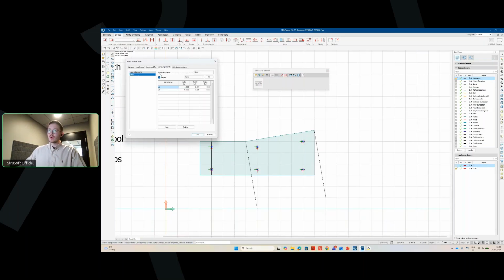No modifications. So here we just delete the second lane, and here I will just create a very large lane, simply like this, that starts at 10 meters and ends 10 meters on both sides of the stakeout line. Here, let's go with multi-start. Maybe let's reduce this a bit.